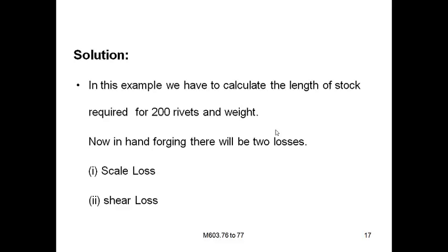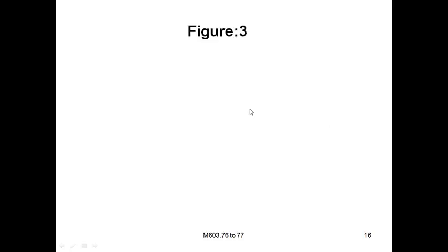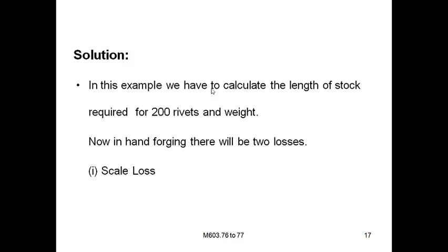Now you see here, it is a draw forged one. Remember, if it is a draw forged one, you need to consider only two losses, scale losses and shear losses.